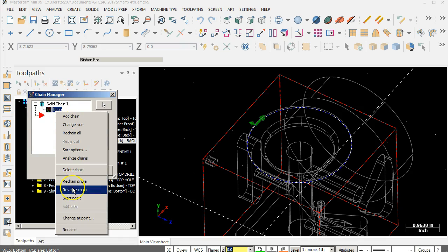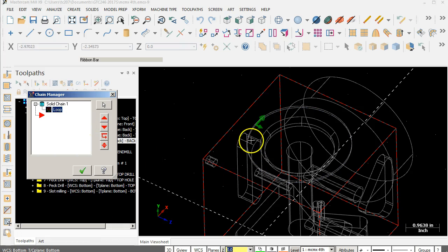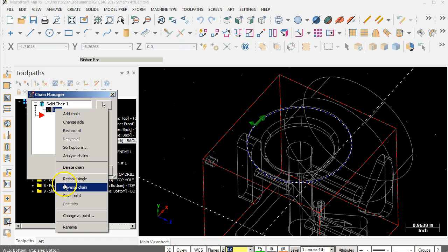So we need to change side. Yep, change side. All right, so I got so wrapped up in the fourth axis, I stopped looking at my direction and stopped looking at my arrow. Now the other side of this just became a conventional cut when I changed side, right? Because we're doing this now. So instead of changing the side, let's reverse the direction.